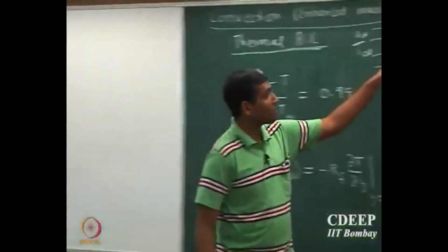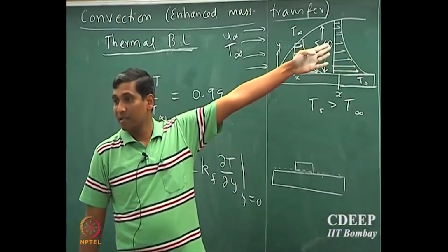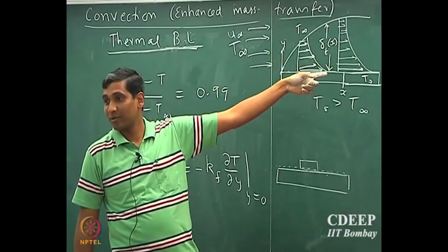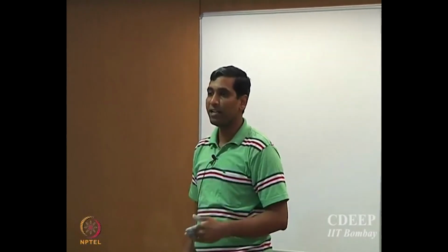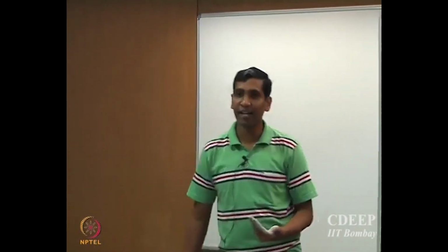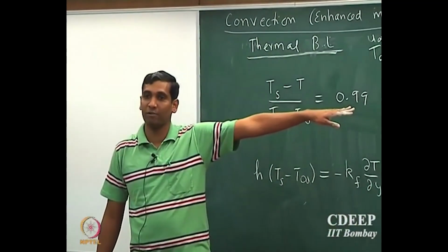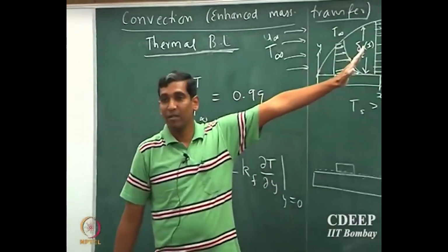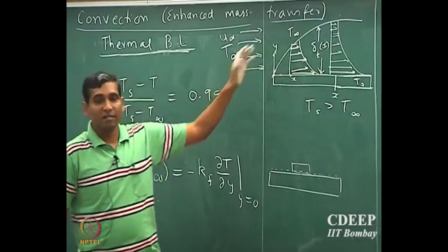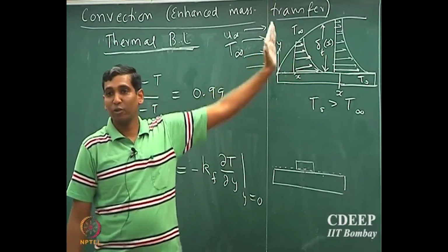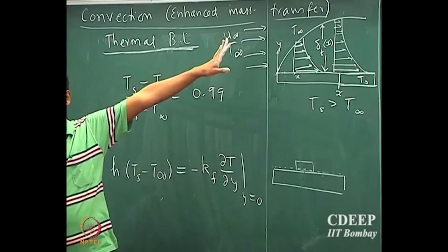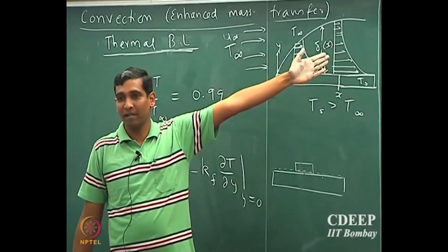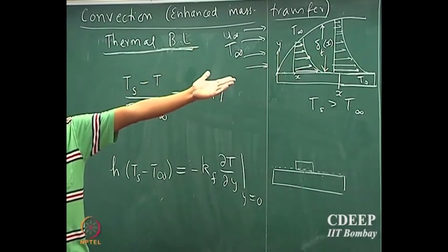That's if you assume things are not moving, but now it's a two-dimensional problem where there are gradients of temperature in both directions. It's not simply heating the fluid; the fluid is also moving, so it's also convected. Unlike the case of a solid where it is pure conduction, here the fluid is also moving, so in the fluid stream there is a temperature gradient in both directions. You can't assume that whatever heat is being transported is simply being used for heating up the fluid. That's not a correct assumption, because convection is also playing a role. It's not a pure increase in the capacity of the fluid.